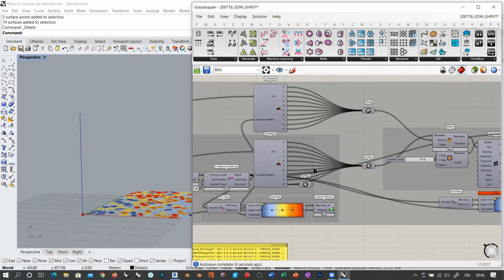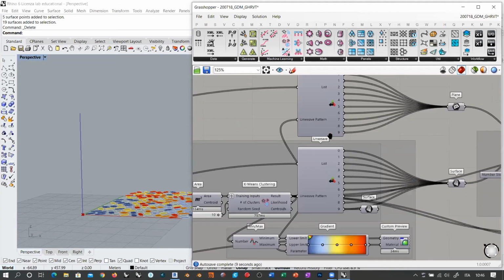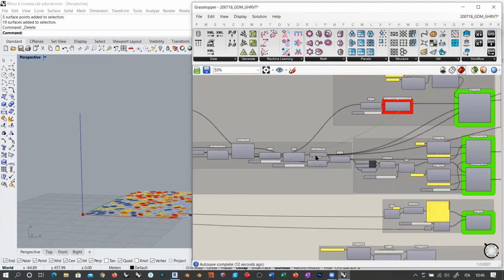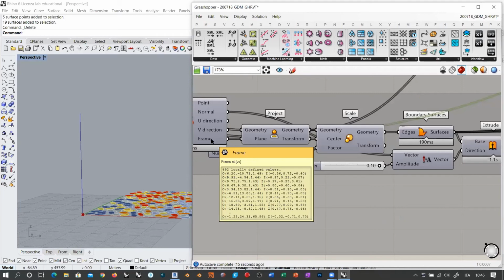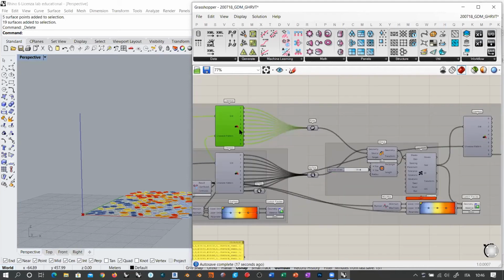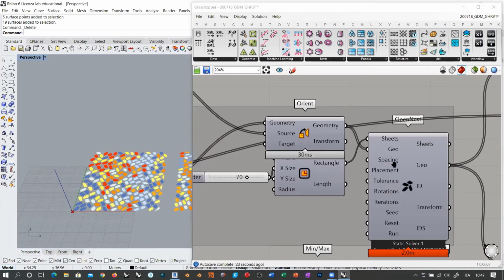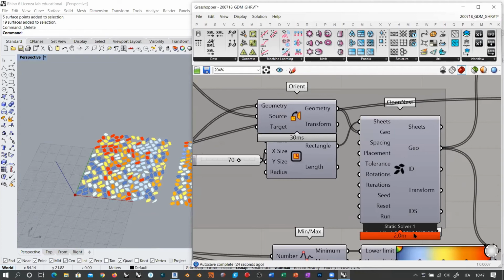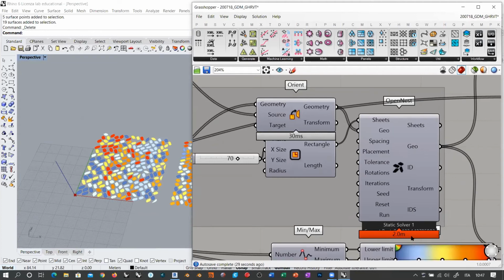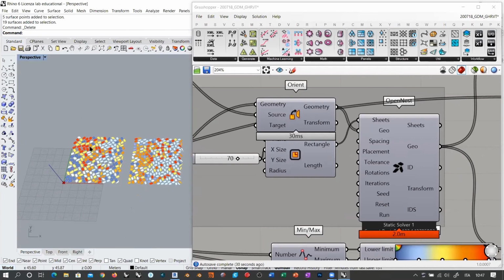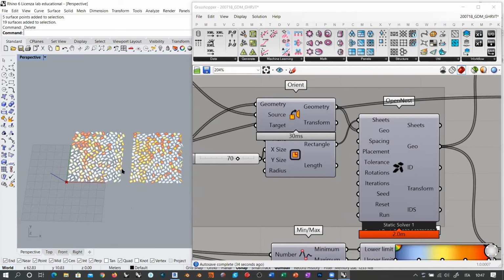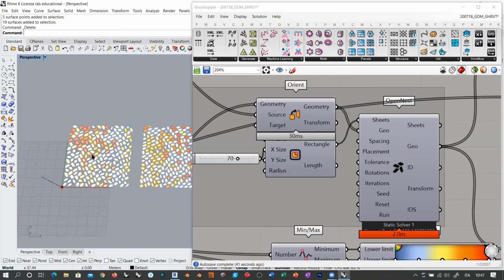I did the same thing, unweaving with the same pattern. This time I unweaved the frames. And you might wonder why, because I was then reorienting the panel on the horizontal plane in order to use OpenNest, which is another plugin, the one that was taking, well, 2 minutes actually, to optimize the positioning of the panel inside a flat sheet of material. This is important for production purposes.